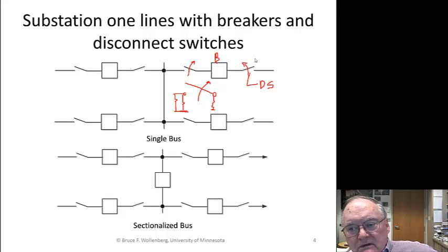So once the disconnect switches are opened to isolate the breaker, we can take a cable, connect it to the breaker itself, and connect it down to ground. And that's the purpose of the disconnect switches, to literally give it electrical isolation and then ground it. Once it's grounded, you can go in and work on it. It's not dangerous anymore. Nobody should be electrocuted because the thing is isolated and it's grounded.